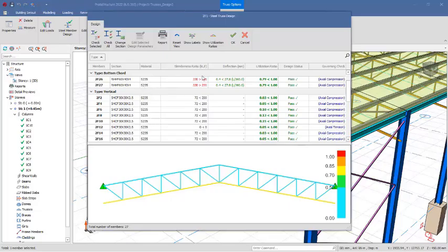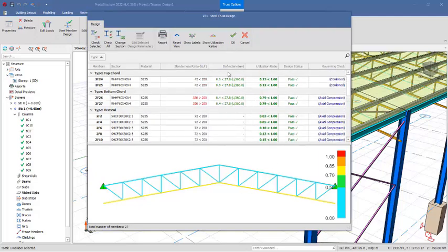To overcome this slenderness ratio, you can increase the thickness of the sections, or make the section less slender by shortening it. I believe this can also be corrected on site during fabrication. So the steel trusses are quite okay. Click on the OK option.